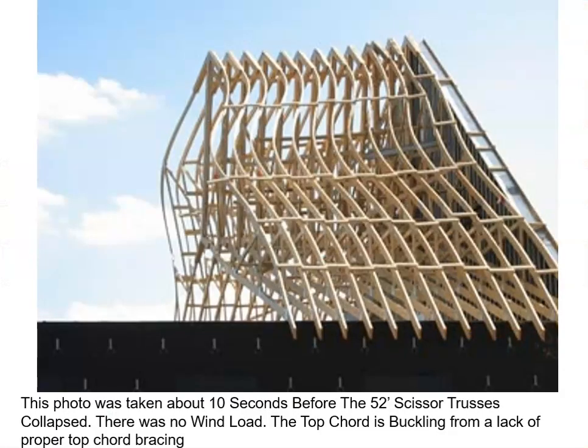The installation of trusses is a very important matter, and there are a lot of safety concerns with that. This photograph was taken 10 seconds before these 52-foot scissor trusses collapsed. No wind. The top chord is buckling, so we see some intense buckling from a lack of proper bracing. Not braced properly. There are a lot of safety concerns and proper procedures that need to be followed on the job site. Obviously, hopefully this gave everybody enough time to get away from this.